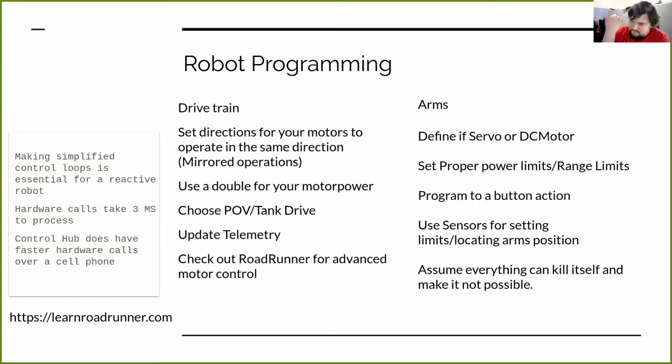So if you have a linear lift and it's autonomous in its function, and you have software limits, it's going to hit that software limit every single time consistently. And so you can use those software limits for programming your autonomous. And if you tie that to a sensor as opposed to an encoder, you can use a color sensor to detect distance, because you could put different colored tape on your arm and have a color sensor.